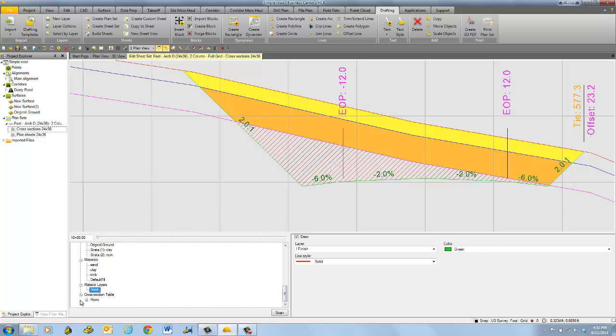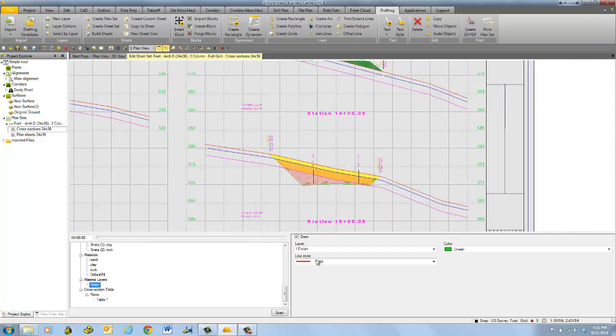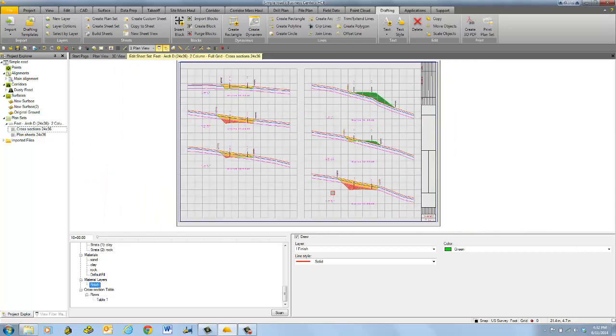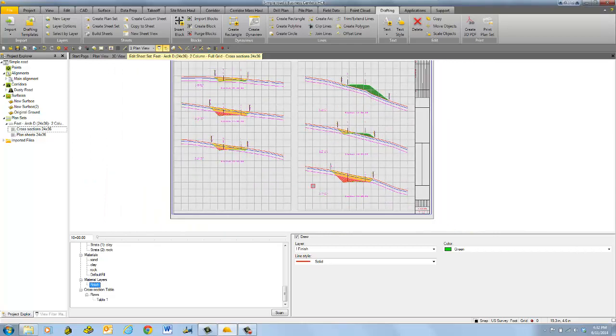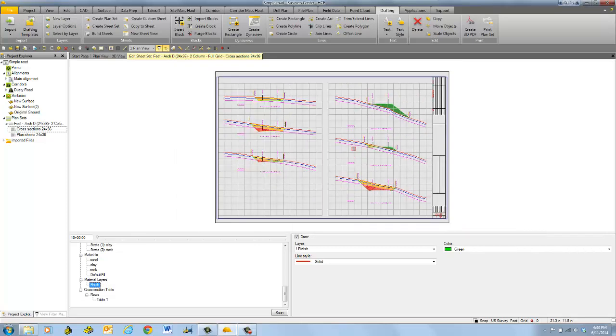Now, there's a different style of labeling sheets that's used more in Europe with the drop labels. The very last section in the settings allows you to configure what those are going to look like. We don't include that in this specific example, but again, it's just as easy to make a few changes and see how it's going to affect your sheet. The templates that are in the metric sizes all make use of the cross-section table and drop lines and labeling cross-sections that way. So this is a real quick overview of how cross-sections work.